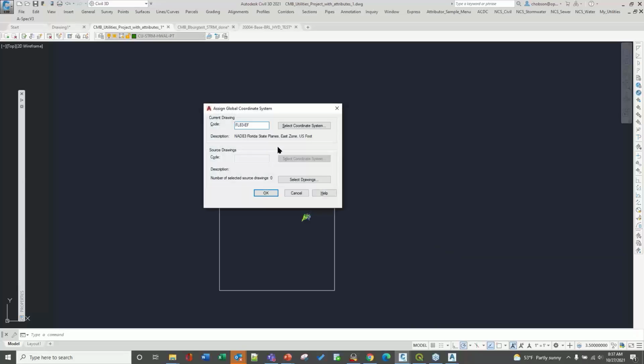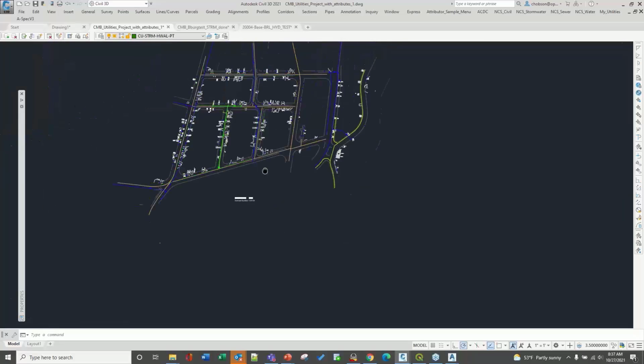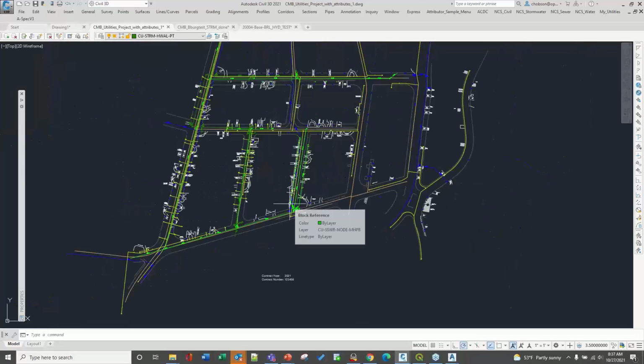So if this was a state plane, in this particular model, this drawing actually has a coordinate system set. You can see it's a Florida state plane, and so these are feet, and we'd expect the min-max extents to be within the boundary. So that's useful. You'll notice that this is in fact georeferenced. So that's one thing we check on there.